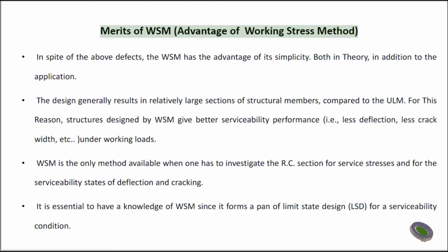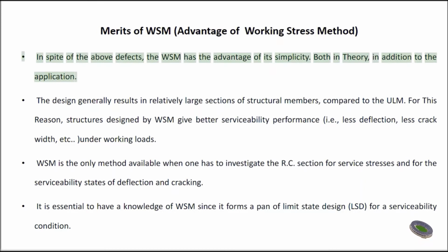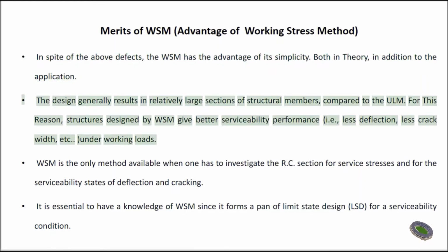Merits of WSM, advantages of working stress method. In spite of the above defects, the WSM has the advantage of its simplicity, both in theory and in application. The design generally results in relatively large sections of structural members, compared to the ULM.